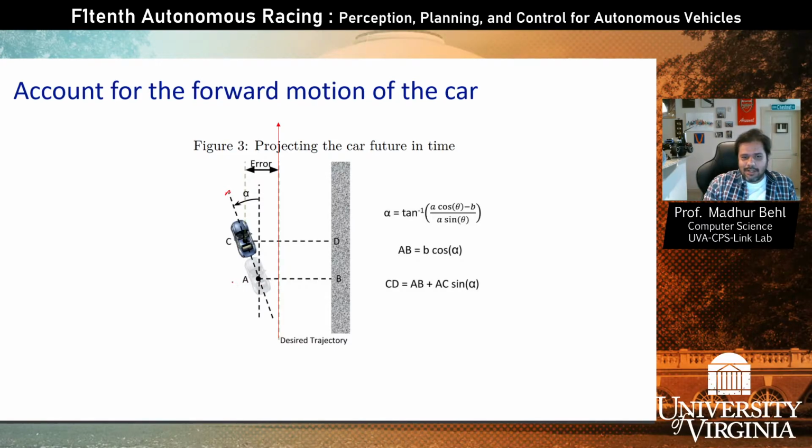Currently my car is at A, and let's say at time t equals k, my car is at position A. I don't know the coordinates of this point A, nor do I need it for this algorithm, because all I compute at time k is this measurement AB from the previous equation. However, at time k, I am projecting the car a certain distance, let's say L, along the same heading as is currently given by the car. So we know alpha at any point.